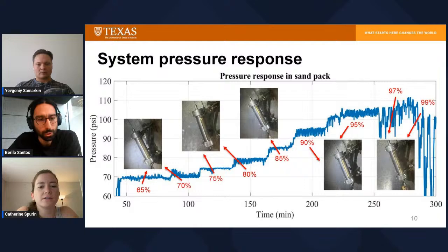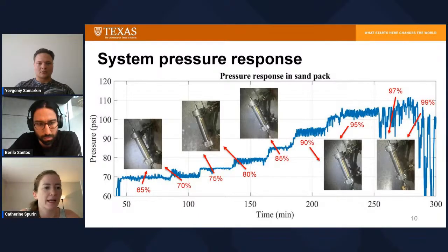Yeah, I would be interested to see if the magnitude of the fluctuations could be correlated to the amount of dynamics that happen from the foam or the gas in the porous medium. I'm wondering as well, can you from these experiments determine how much of the foam channels through, say, the high perm region? Do you think it's full channelization, or do you think it's the majority in the high perm region? Is this something that you were able to quantify?